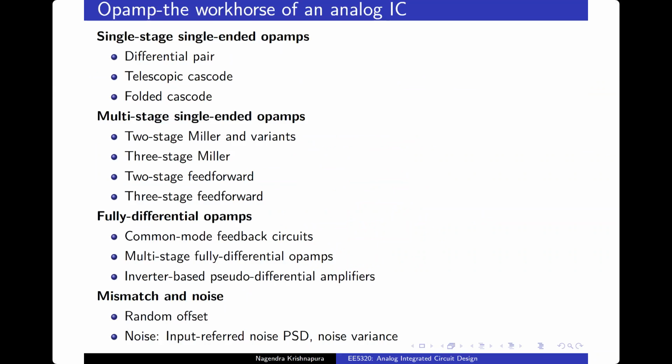And slightly related is also distortion. That is, you're not likely to use it very often, but you want to calculate something finer than the swing limit, but you still want some idea of the nonlinearity. But you don't want something as crude as swing limit to saying that, oh, this is the maximum I can apply. Because in reality, as you increase the signal amplitude, it's not that it behaves linearly up to some point and then it stops, it starts misbehaving. So the distortion components go on increasing.